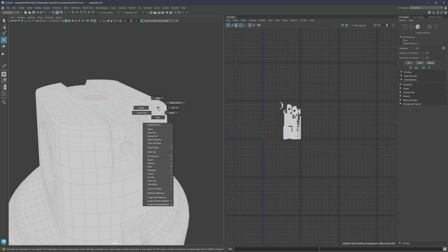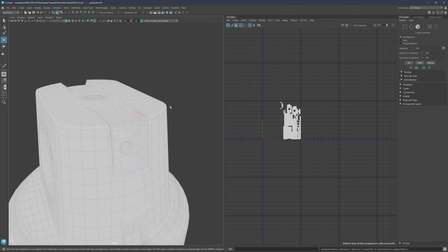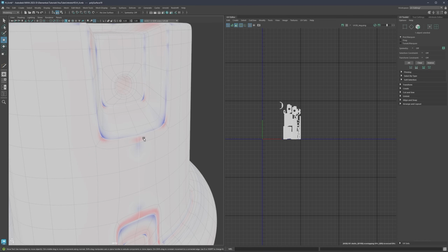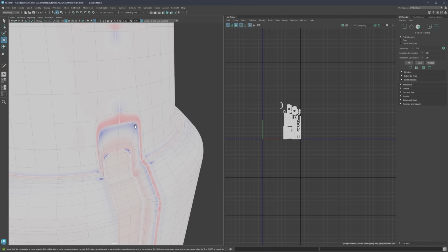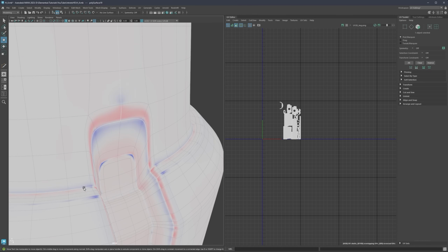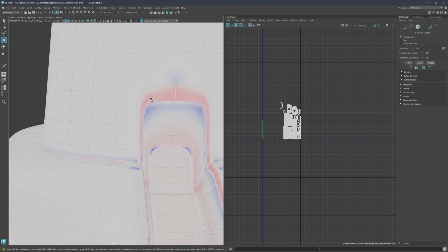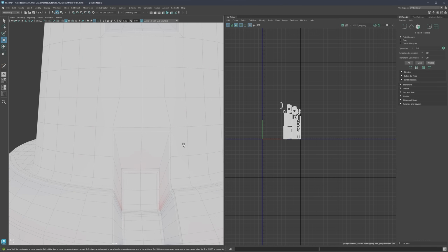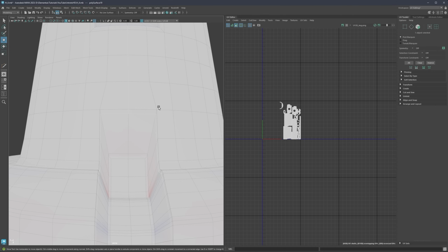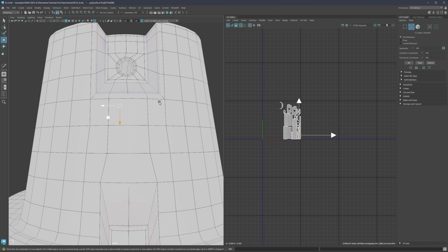The true test is going to be on Subdivision preview, where you're going to see that the most stretching or compression in our case is going to be located between those support loops. So support loops and structural loops, and especially here, if you remember, we mentioned that we forgot to add one extra support loop like we have here on the top.